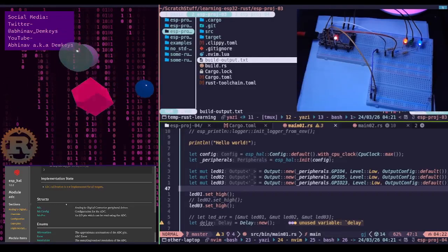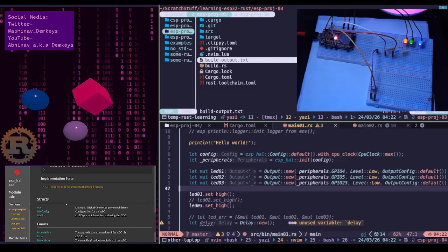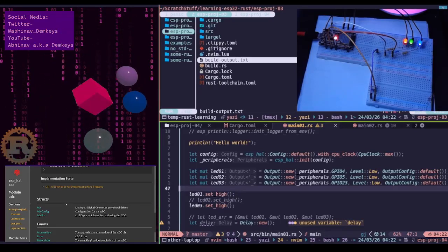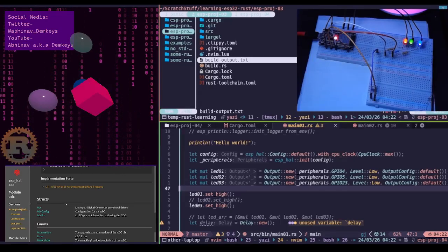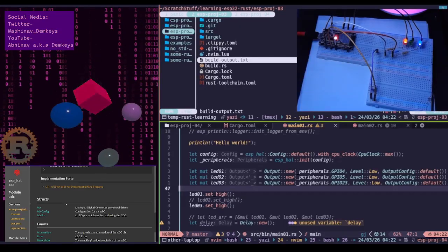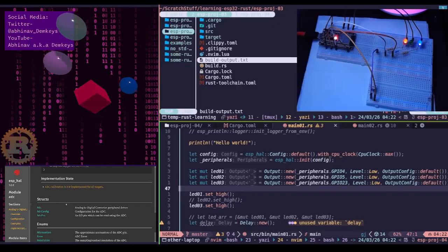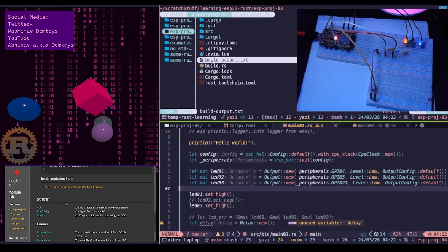On the original ESP32, the hardware is natively 12-bit, meaning the internal successive approximation register breaks the voltage into 2 to the power 12, so 4096 steps. However, in practice, you will encounter two different ranges depending on how you configure your code. Configurable bit width: the ESP32 allows you to downsample the resolution.